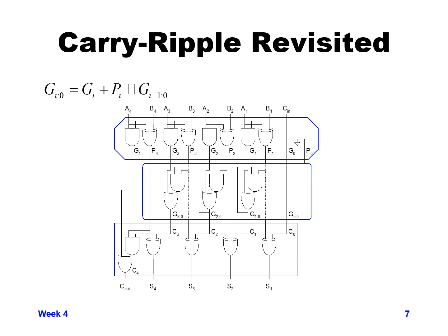We have that propagate and generate that we're using instead for each bit, and then rippling the carry through. But this design still causes us to have, for every bit of the A and B data, one extra stage delay of your carry rippling through your adder. So you can see that this overall design, as is, would be fairly slow, waiting for the carry.